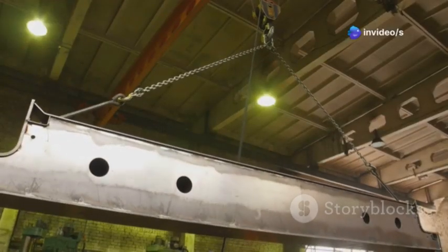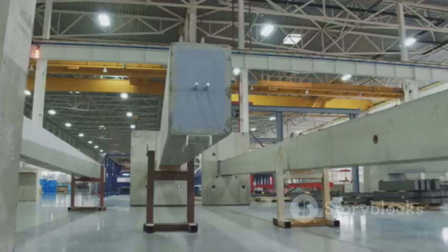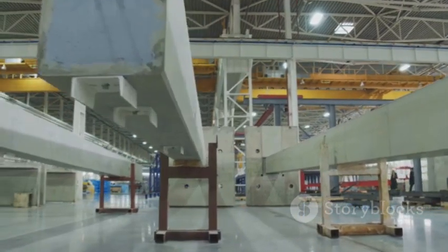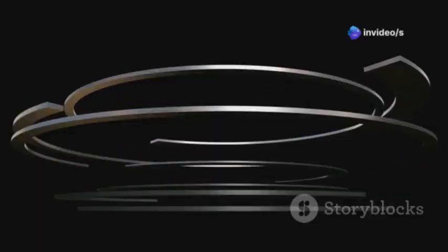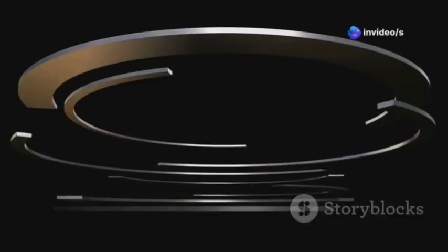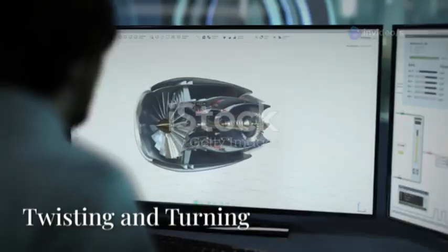For instance, consider a beam supported at its ends with a heavy object placed in the middle. The shear force will be highest near the supports, where the beam is resisting the load's downward push. As we move towards the center of the beam, the shear force decreases, reaching zero at the point directly below the load.